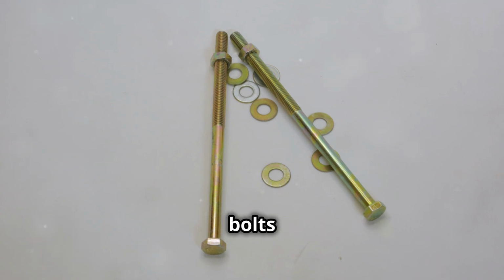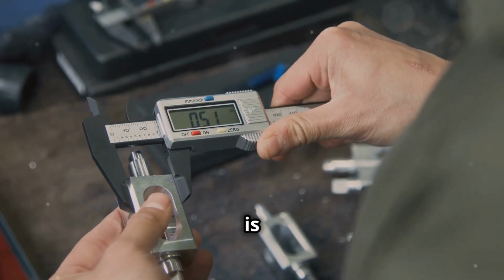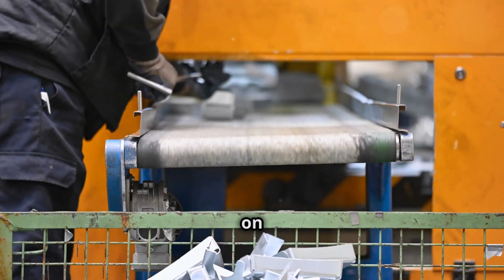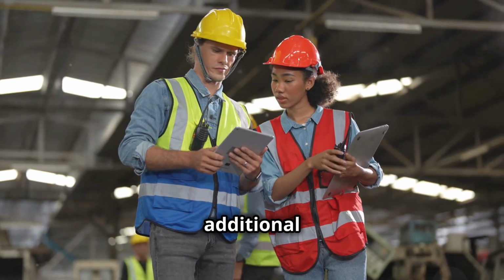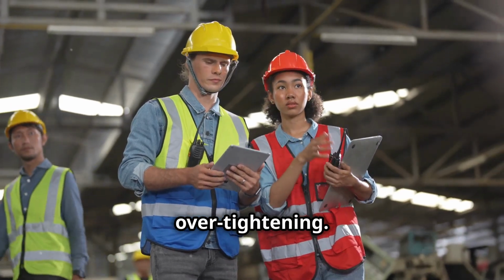For over-tightened bolts with an RPN of 108, the action is to improve tool calibration procedures and train operators on correct bolt tightening methods. Introduce additional inspection steps to check for over-tightening.